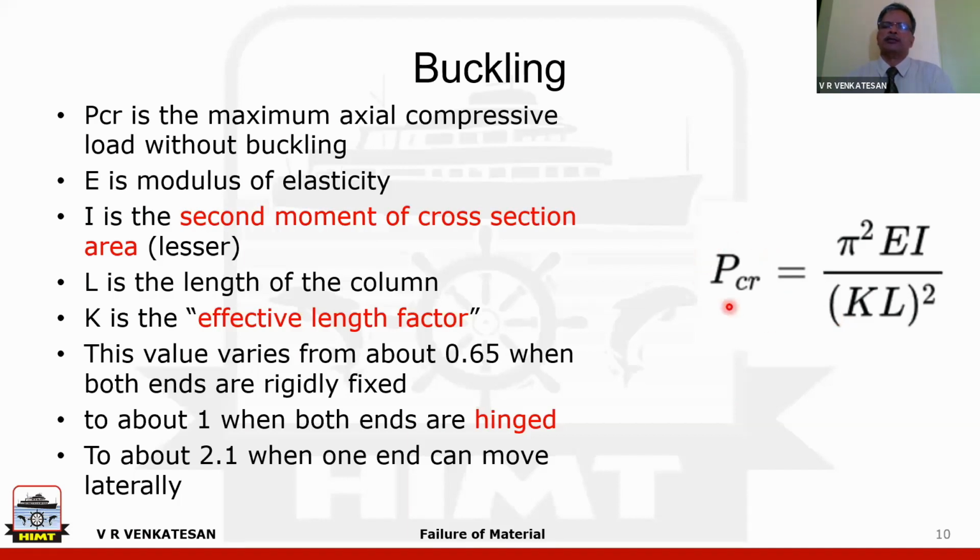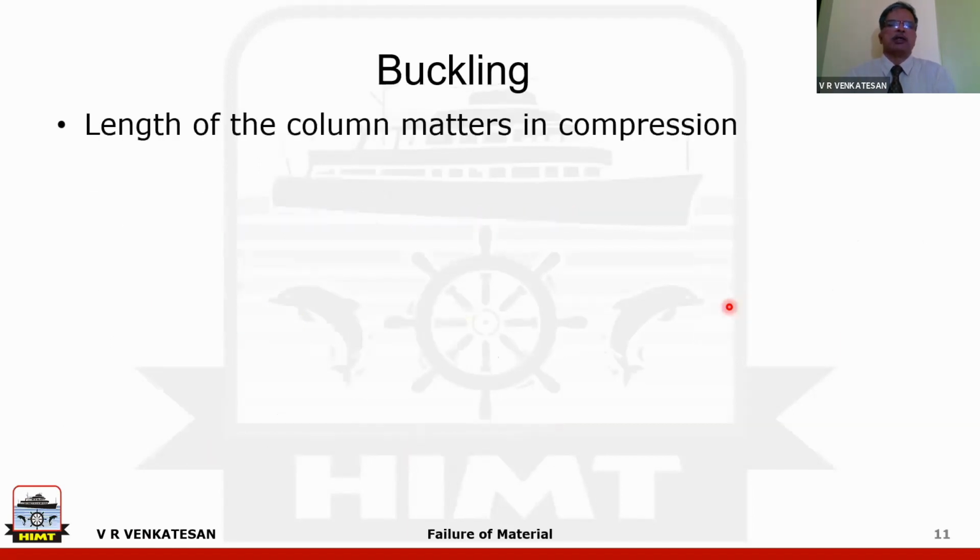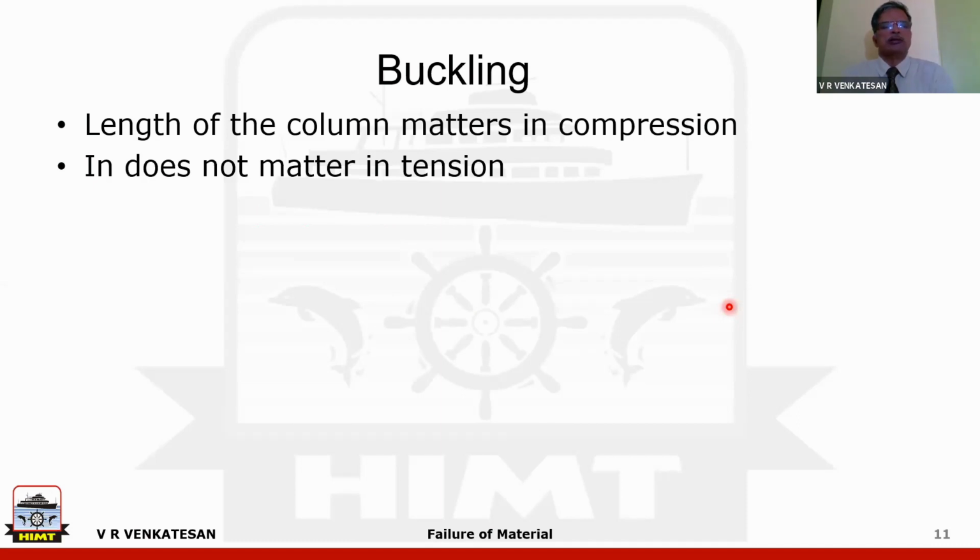be taken. Now, one of the important principles you will understand here is when a component is put under tension and when it is put under compression, behavior is not the same. There are a lot of differences. In the case of compression, length of the column will matter. If the same thing is under tension, it does not matter at all.